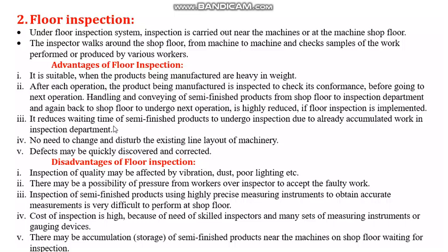Then the third advantage is that it reduces the waiting time of the semi-finished products to undergo inspection, due to already accumulated work in the inspection department. Sometimes the worker may say, you inspect and give this, then only I can proceed further. But the inspection department already has some parts to be inspected, and they say you keep it and wait for some time. The time is wasted if it is taken to the inspection room, whereas if they are doing shop floor inspection, that time is not wasted.